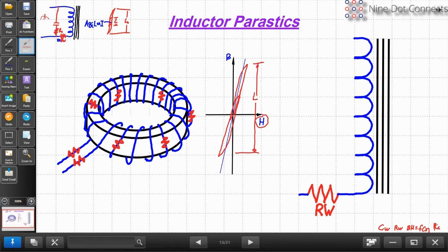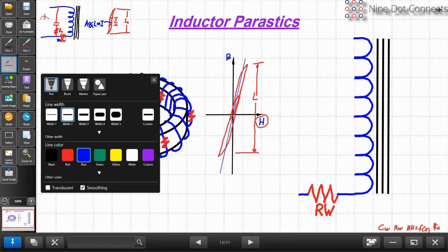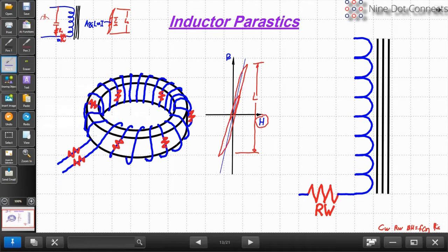Therefore, these loss effects are going to be basically proportional to the amount of current, and they're proportional in such a way that the best way to take them in, okay, we need to put them in a different place than the resistance of the winding if we're going to talk about a model. So you will have here a whole bunch of little capacitors between the windings. Because these little capacitances exist, you'll find that it's necessary to handle them in some way.